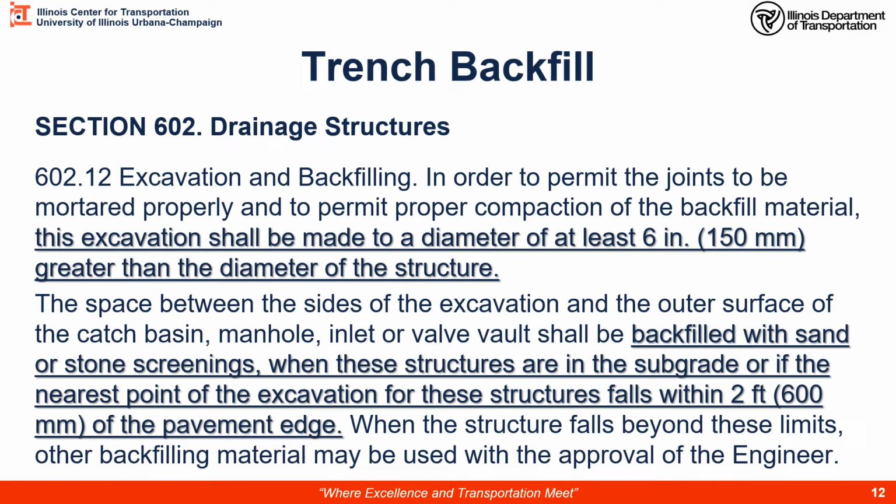So if you have a manhole, at least 6 inches beyond that, diameter-wise, will be backfilled as part of that work. So that is incidental to that manhole. We don't want to pay for that backfill twice, so we will have to deduct that from our trench once we get into that calculation.